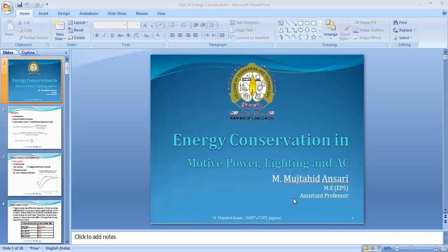So the maintenance free is there. There is no sparking over the brushes. Such type of motor is most popular in the petroleum industry, chemical industries, and where some ethane, methane gases are there, so there is no such type of sparking over the brushes. These are the advantages of the three phase induction motor.